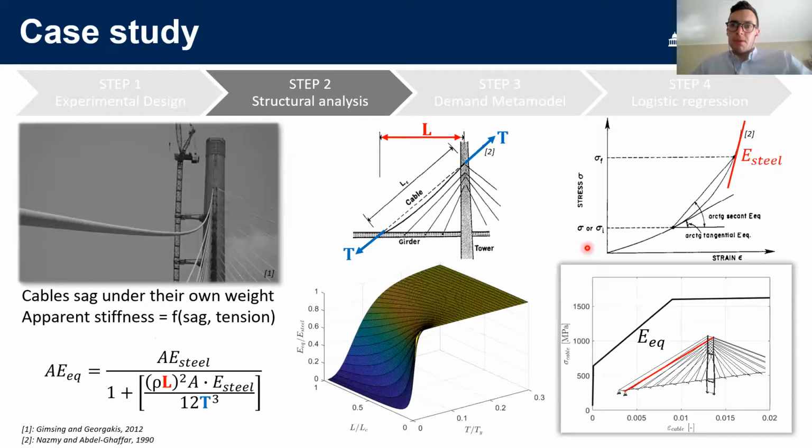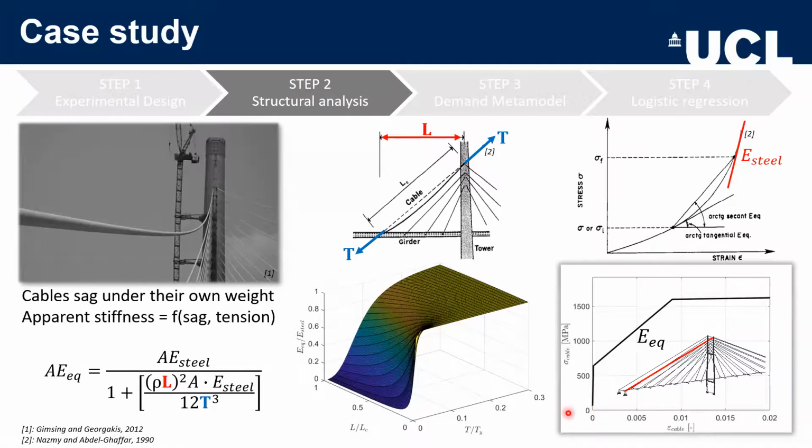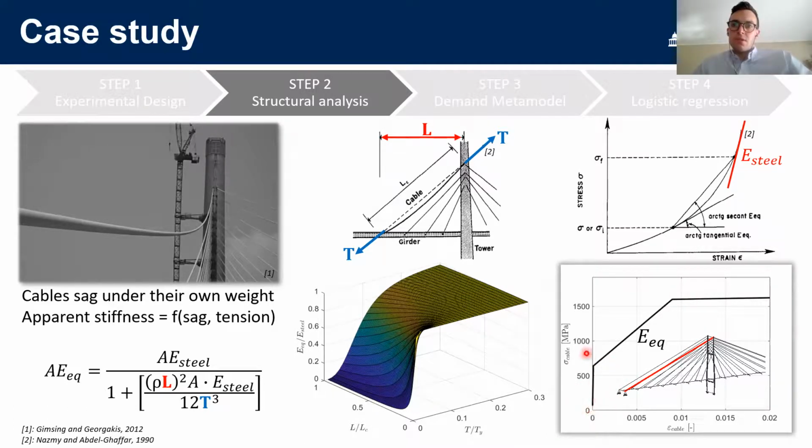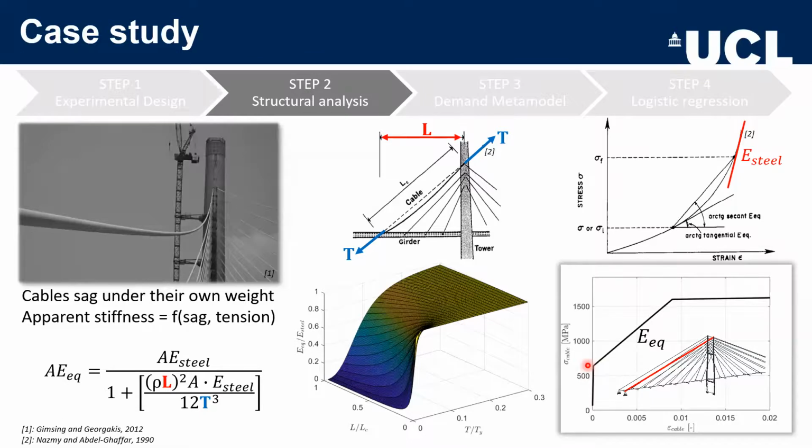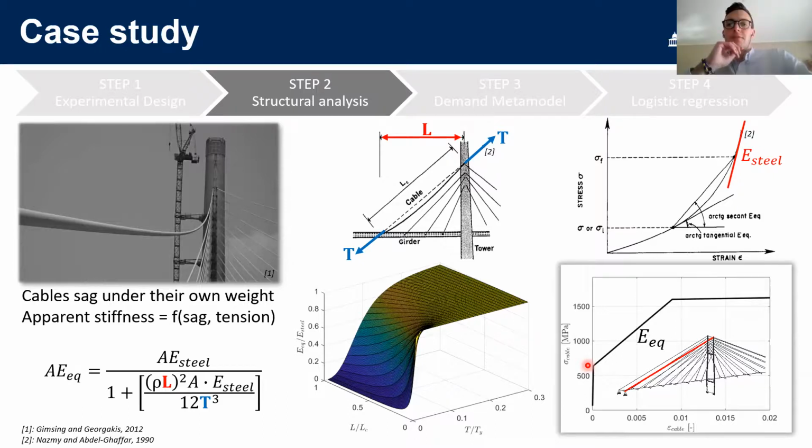And I also remember the last question you made was about the stress in the cables. That's right. Yeah, it is included in terms of this constitutive law. So you see this value at the beginning represents the initial stress inside the cables, which might be optimized, or in my case, I just obtained that through iteration over the gravity loads. And I see now here that there is a pretension in cables also. Yeah, exactly. Okay, thank you very much. Thanks for your question.